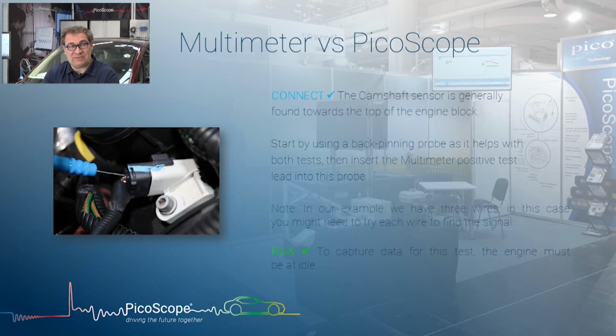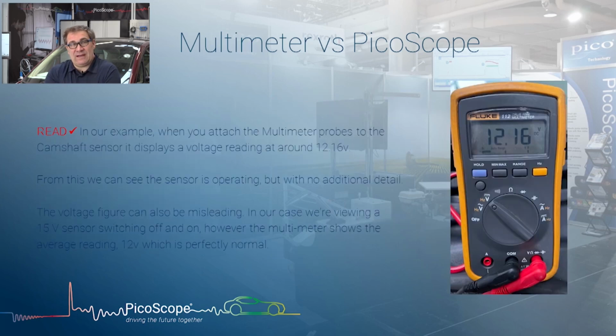Normally, the most standard way would be to use a back pinning probe. I think in Phil's case, he's going to have used a breakout lead. We're just lucky to have all the breakout leads for the right components here set up. So we're going to connect in and we're going to run. So effectively, we've got to have the engine running on idle to capture our data. And then read. So when we look at our multimeter, there we go.